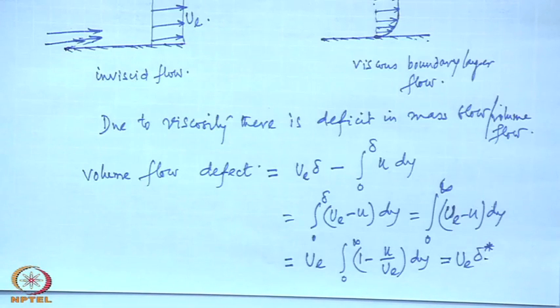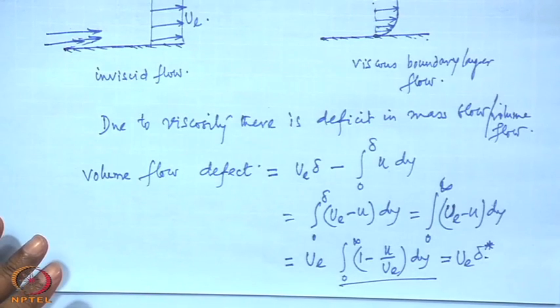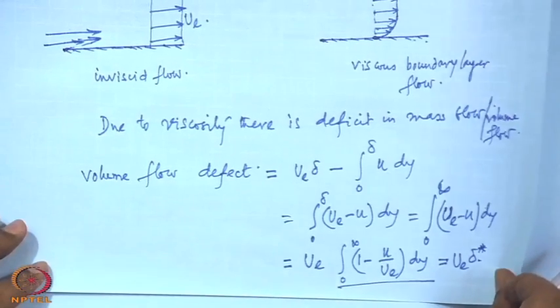So, that is another effect of the boundary layer: the equivalent effect is that the wall thickness has increased by delta star, or the wall is displaced by a distance delta star, and this delta star is called the displacement thickness. And as you can see, it is a very easily measurable quantity. You will be measuring delta star in your experiments later.